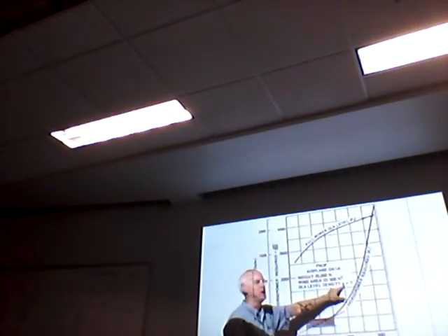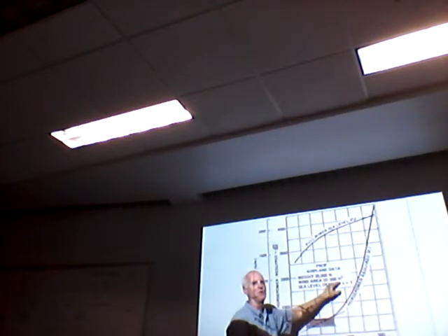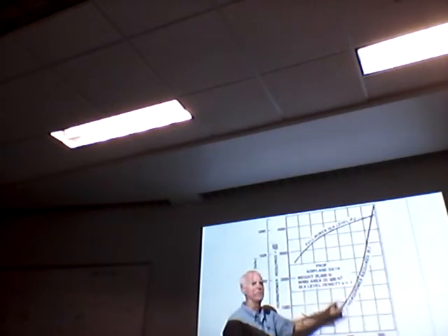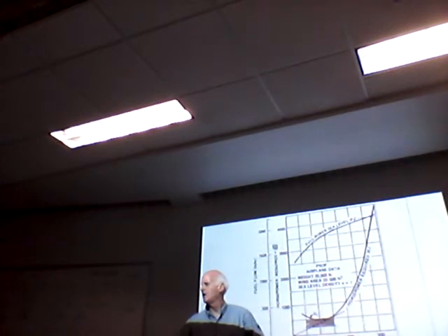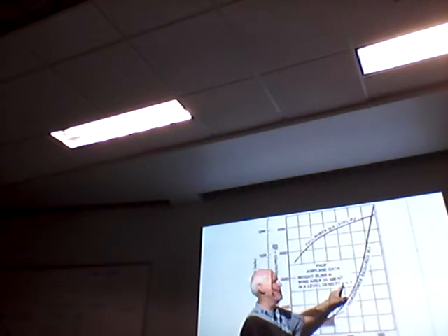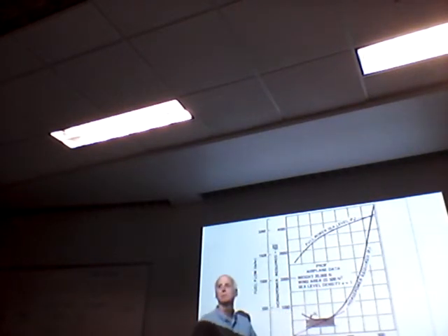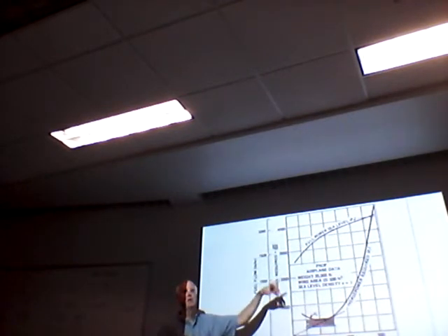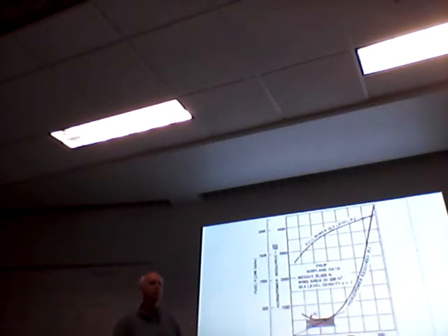And by the way, if you ever have to do a formula problem, when I go over the paper part of the test, we'll figure that out. But remember, if I give you sea level, then you don't need the tables or anything for this, it's just 1. Sea level density ratio is 1. So if you see that sigma in the formula required, just plug in a 1. Pretty easy.